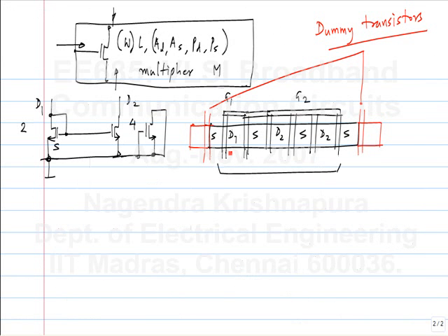And you can do similar things, these dummy transistors, and also using a single common diffusion area when you have other structures, like for instance, a differential pair, you do the same thing. So again, this comes into the picture only when you start doing layout. I don't mean that when you have a differential pair in the assignment, you make a complicated layout and then calculate the area. You can just assume that there are two independently laid out transistors. For instance, here the source is common. So you can use that fact to make a more compact layout.